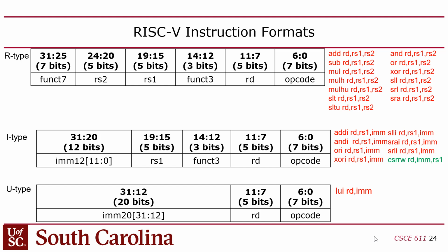But I guess somebody looked, and most immediates tend to fall in that 12-bit dynamic range. So, someone decided that 16 bits was too many for the immediate. So we deleted 4 bits from the immediate, but then we added a 3-bit function field, and we added 1 more bit for the opcode, I guess, is the trade-off there.